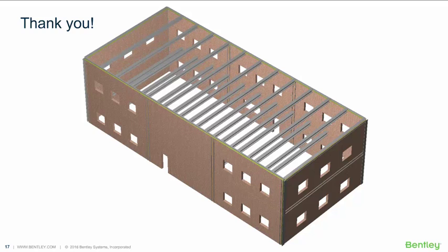Okay, there's a follow-up to the question about importing just the lateral or the full model, asking if the design combinations that include gravity loads do not get imported. No, they will. Even if you just specify the lateral system, it's just about the elements that are being imported, right? Beams, columns, and walls. The combinations will come. It doesn't matter.